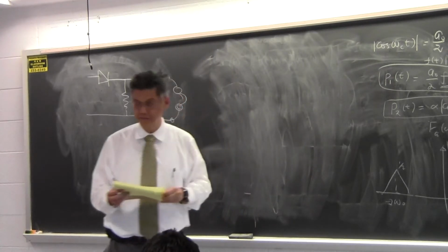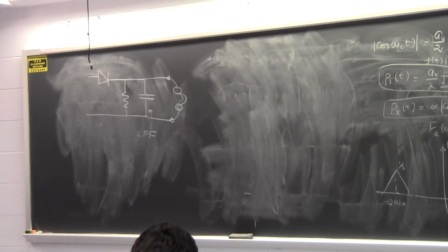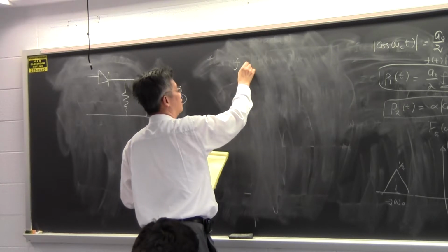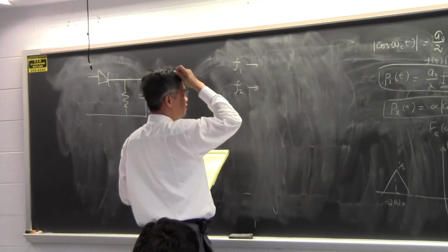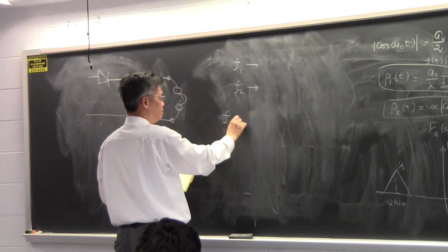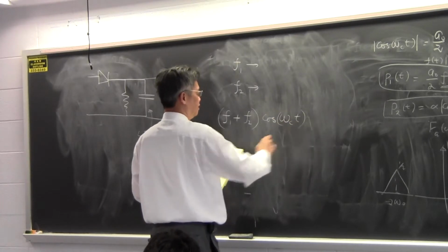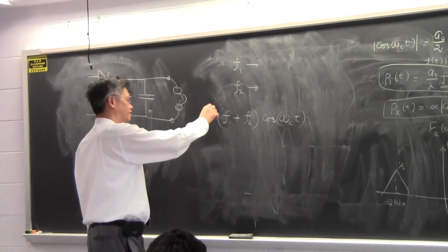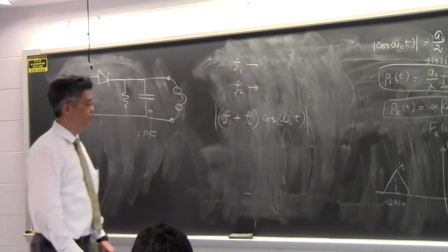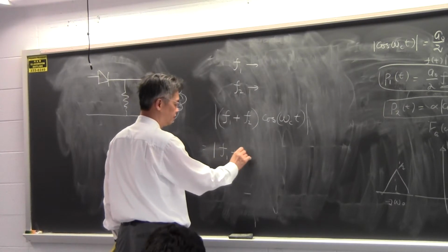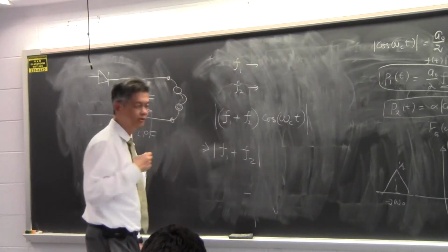Then there's a question in the book that asks if envelope detection is a linear process. Is it a linear process? Well, say if I have two signals, F1 and F2, and if this goes through my system simultaneously, then I will modulate it with this thing, and then I will do envelope detection, and I try to extract only the amplitude part of the signal.